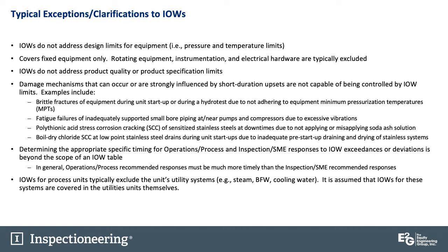And then finally, IOWs for process units typically do exclude the unit's utility systems, although you should have IOWs for your utility systems eventually. It is assumed that IOWs for these systems are usually covered in the utilities units themselves, and that's how most refineries do handle that as well.